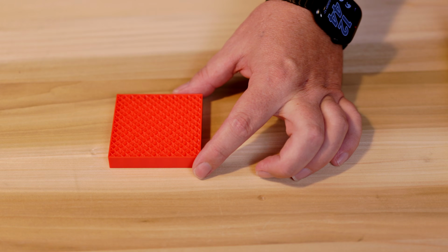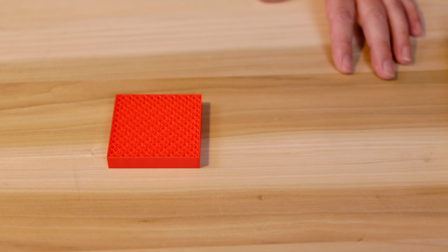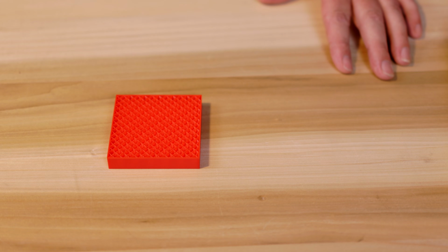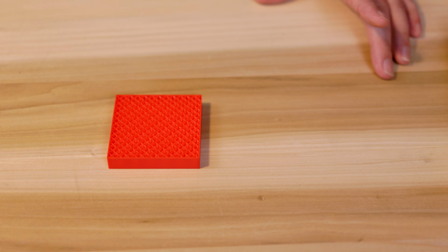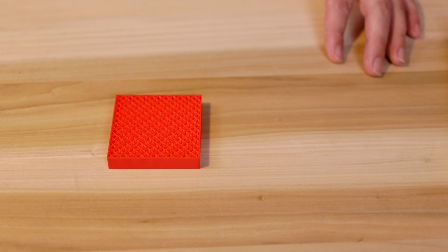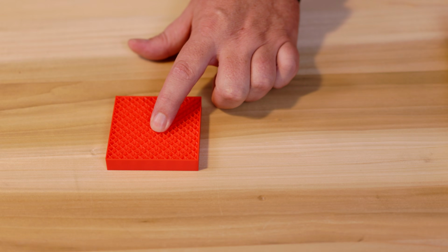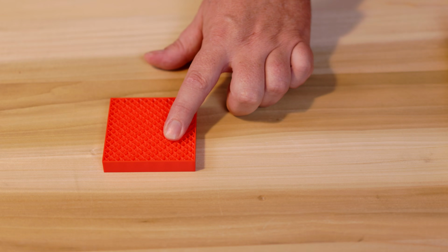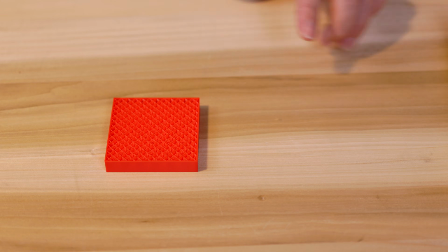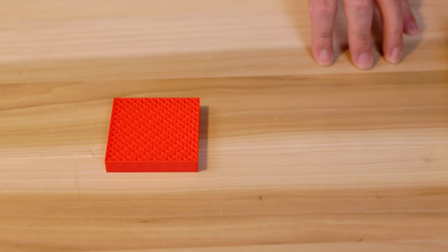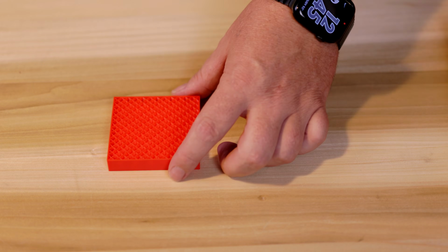Next is rectilinear. Rectilinear consists of straight lines running back and forth in a single direction, changing directions in each layer. The use case is for general purpose printing. The pro, it can be quick to print. Not the strongest pattern would be the con, and use higher densities for improved strength if this is something that you want to use for general printing. The print time for the cube was 1 hour and 4 minutes, and it was 70.45 grams. One thing to note with this is it is not very flexible. It is pretty rigid, and it is fairly light.